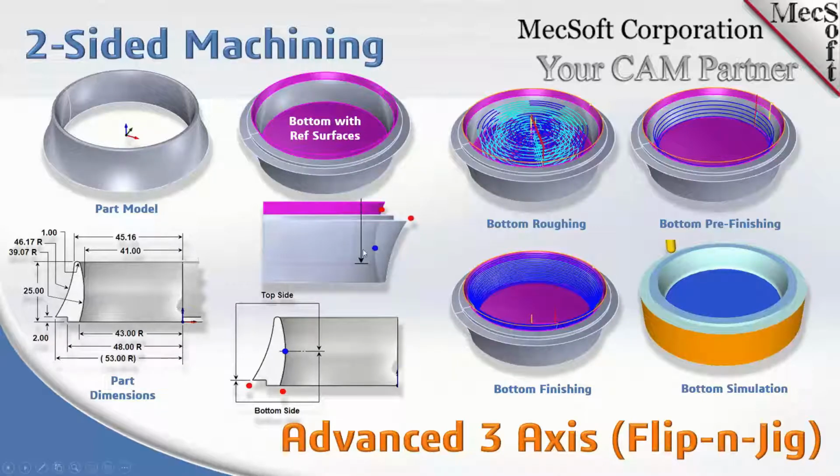So you'll see in the center view here with the arrow coming down, the tool will have to stop on that circular surface right there and not go all the way through. And then the red and the blue dots signify where the parting plane is. In other words, you got to go at least past the blue dot on the inside. And then we have a surface added at one of the red dots so that it guides the tool past this edge. That's what those surfaces are all about.